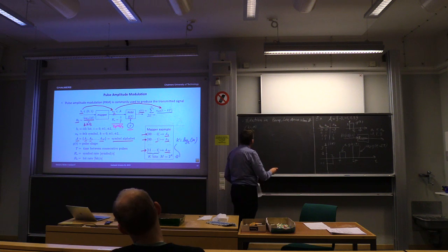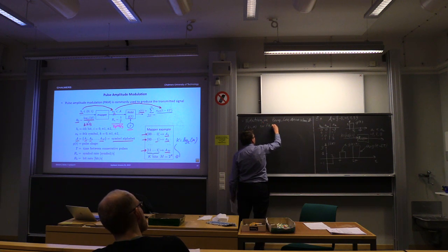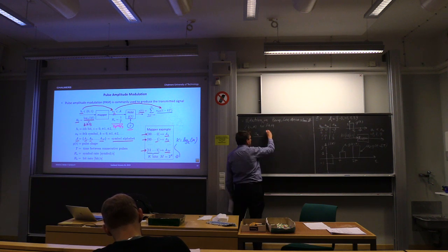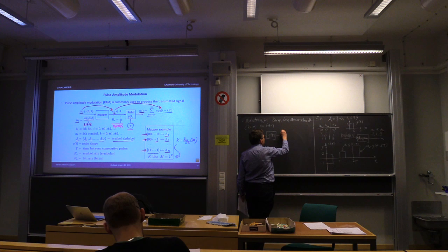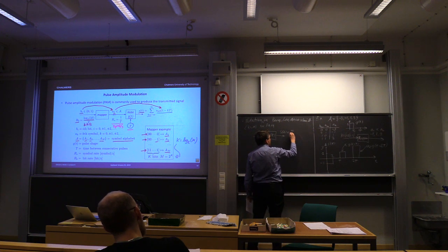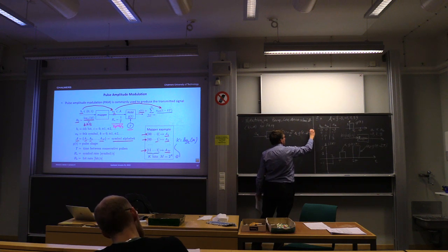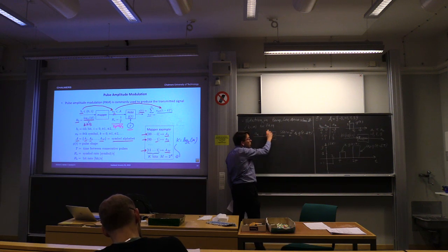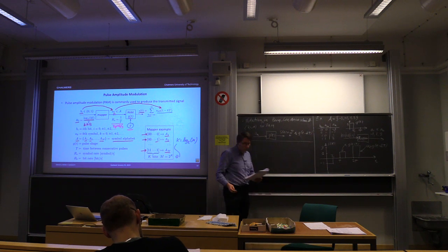It's available for free. The notation for pulse amplitude modulation here is something like this. It's similar: you have your input amplitudes like this, but they simplify and just write g(t) here. And then the output is, as before, the sum over k of a_k g(t minus kT). So it's implicit, capital T is not explicitly noted here, and they don't write pulse amplitude modulation either, as I do. Anyways, otherwise it's the same.